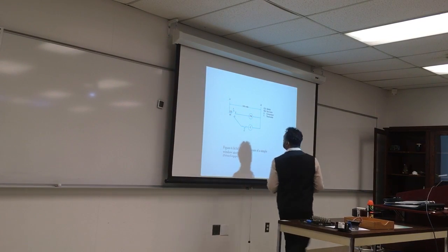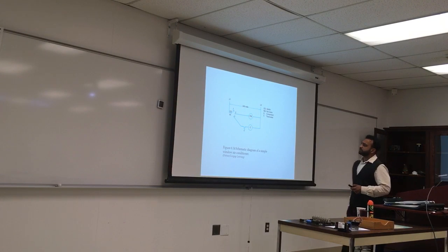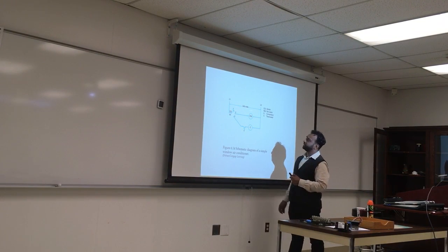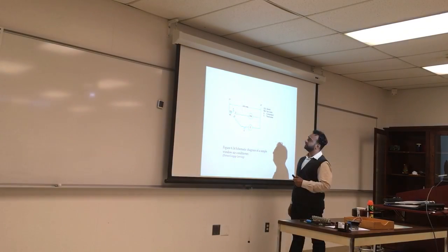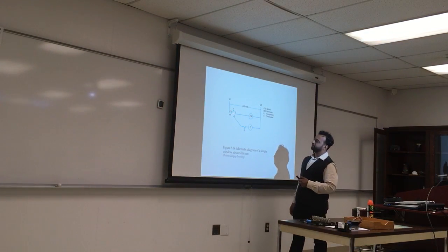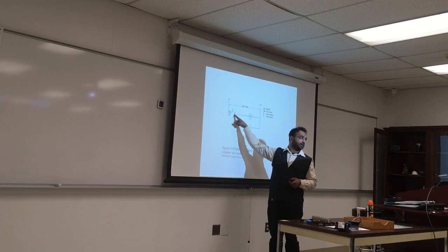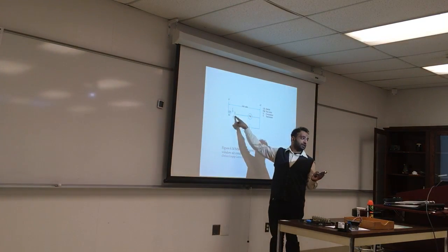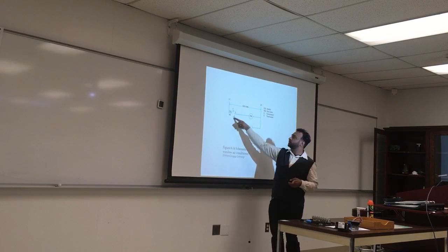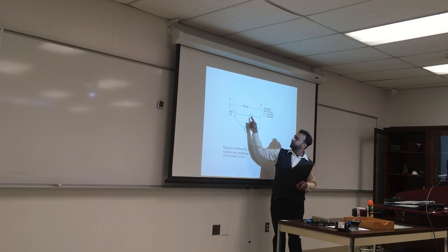This is another AC, a window air conditioner. So look at the switch. First, the voltage between line 1 and line 2 is 240. Fan motor, compressor, thermostat, and we have two modes. If we connect 1 to 2, what do we get? The fan motor, fan only by itself, and you see that option, fan only. If you connect both, you get everything on: the compressor and the fan motor.